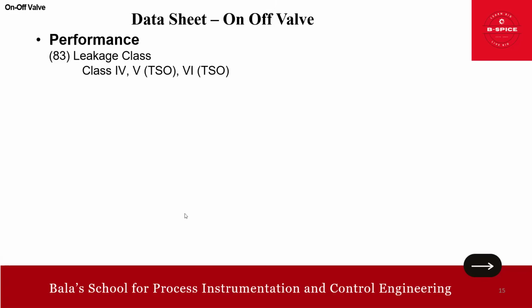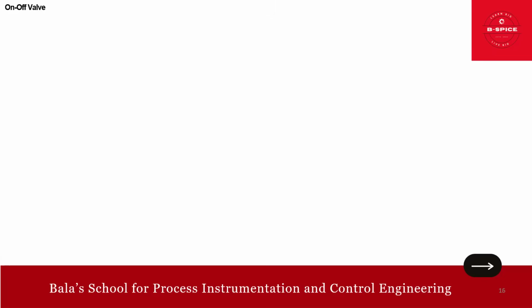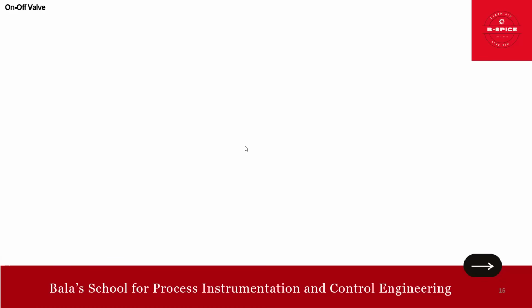Then performance: leakage class, yeah, class 4, class 5, class 6 also, tight shut off (TSO). Then opening travel time, this one as per the process requirement, friends. Closing time also as per process requirement. In fact, I have uploaded a video on this also, the closing and opening time actually. Maybe you can watch and learn from there. Okay, will not focus much here.